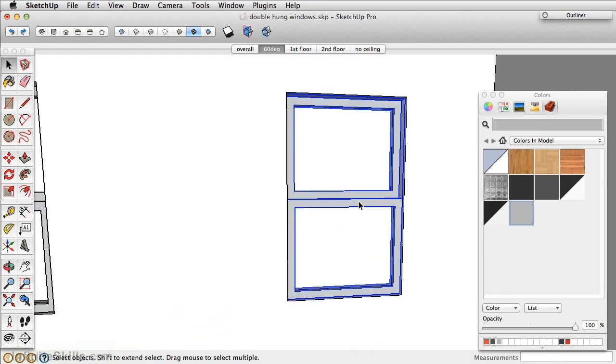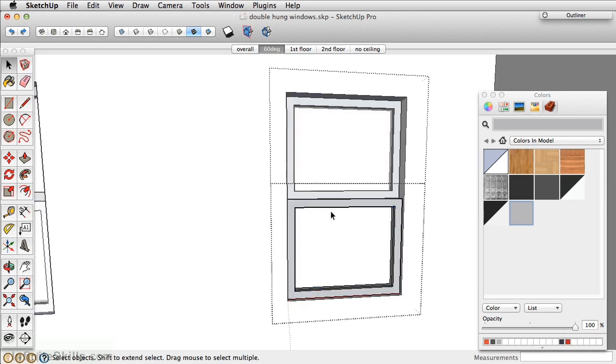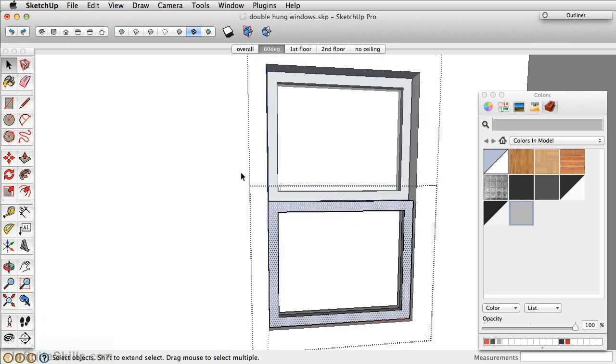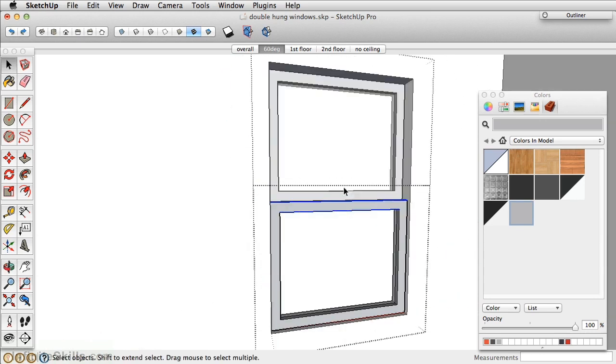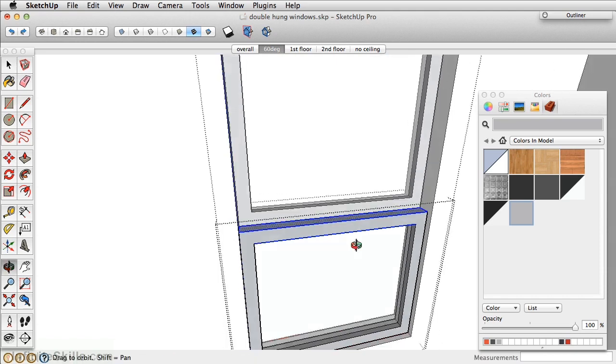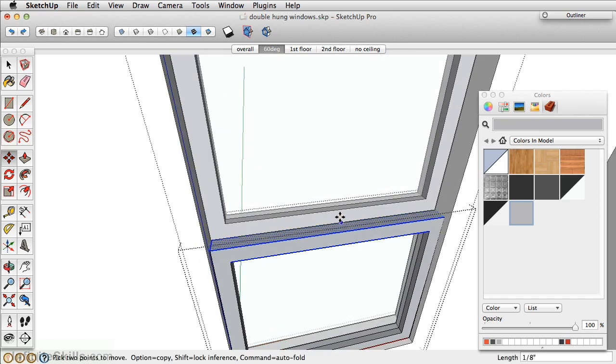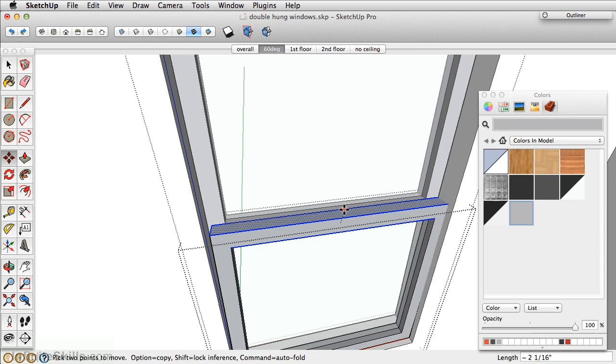The last thing that we notice is that the top face here should actually be up further. So double click again to enter this face. Select a selecting window from left to right around that top area. And then that way it only is selecting the elements in that top area there. Take the move tool and just move this up, making sure you're in the blue axes.